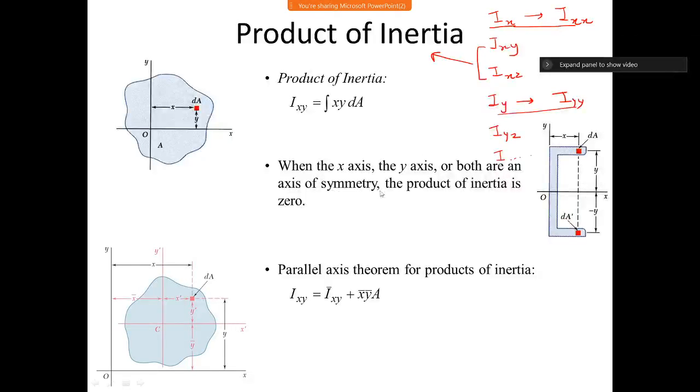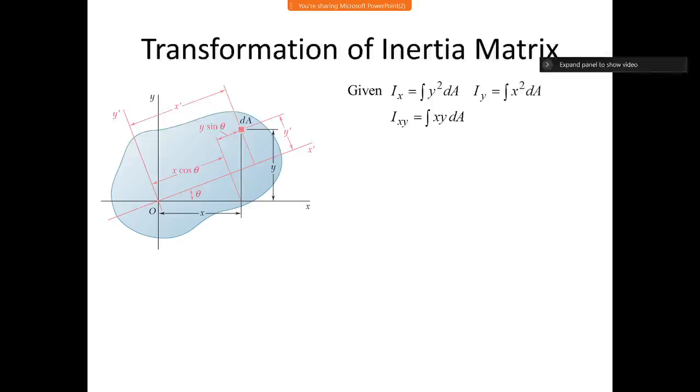So with this basic introduction, we at least now know the definitions for moments of inertia Ixx and the product of inertia, and we know some simple theorems to translate the center. Now the next thing is the transformation of inertia. So when I say inertia, it should mean to you the inertia matrix.